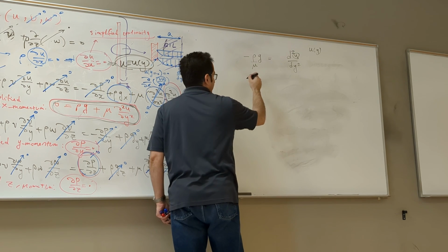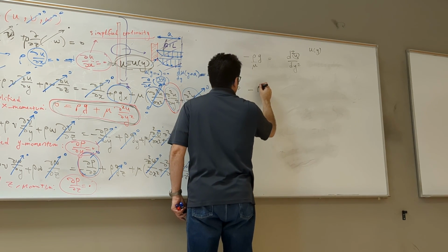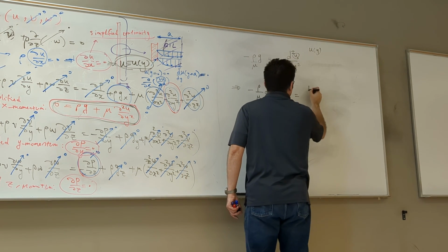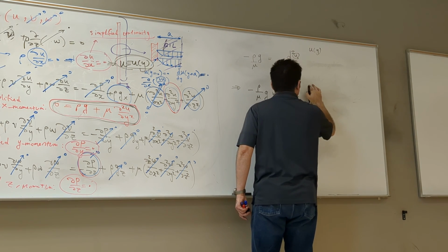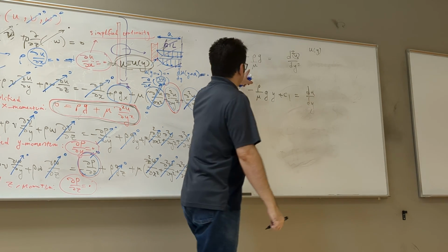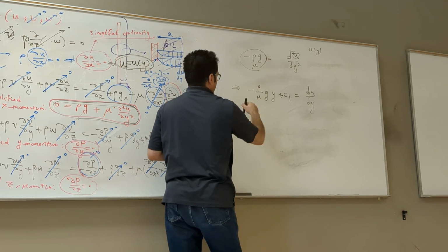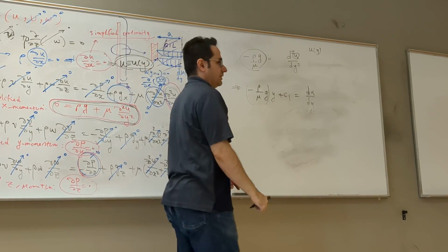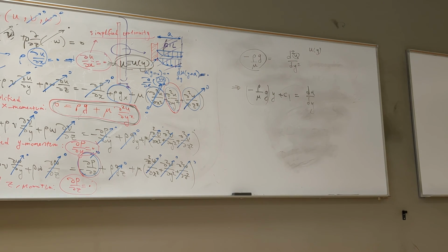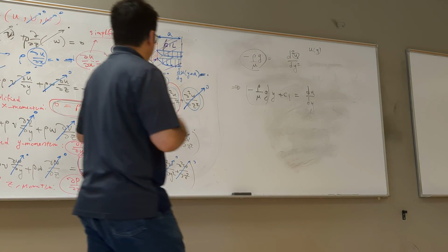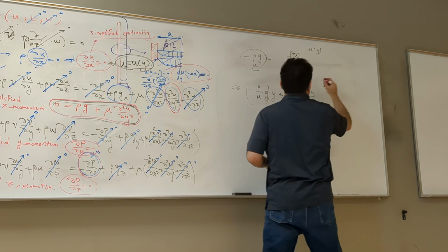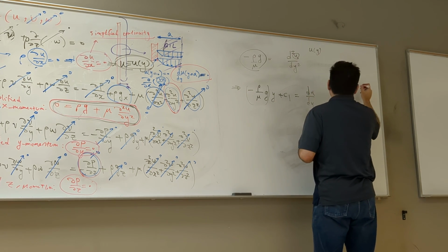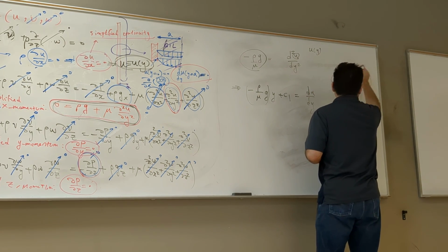and integrate. First integral, you have what? Negative rho over mu g y plus c1 is equal to du dy. Right? So this is just a constant: negative rho g over mu times y plus c1 is equal to du dy. Now what's the boundary condition? The first boundary condition here was du dy at y equal to a must be 0. That was one of the boundary conditions.